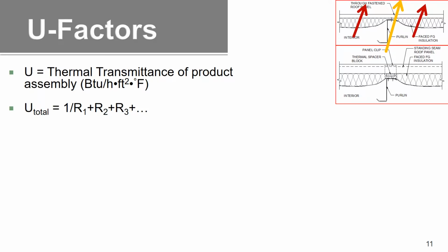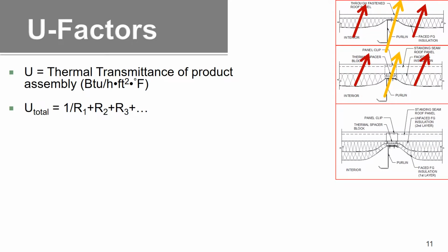I try to illustrate heat loss between framing members and the major heat loss that occurs where there's metal framing, such as a purlin, and the insulation is compressed. The length of the arrows may not be evident to see, reduces on some of these drawings, trying to illustrate less heat loss or less thermal bridging.